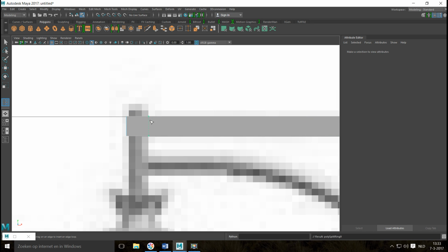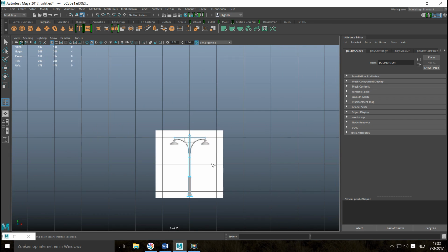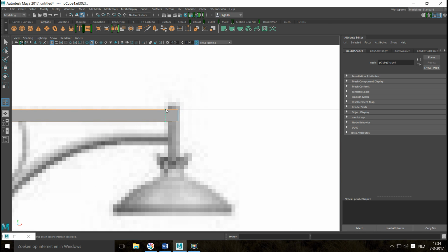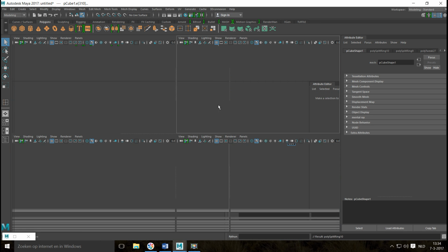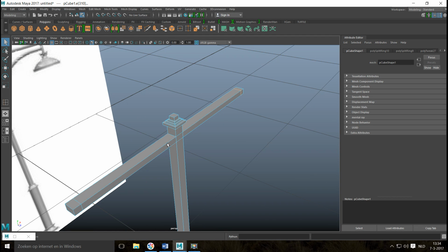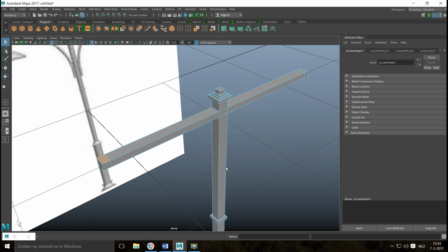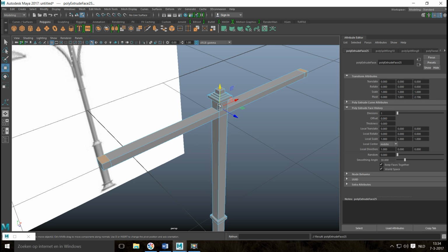and we'll add one here. That's a bit far out. And we'll add one here. Okay. Q on a keyboard. We're going to jump into this view. We're going to right click on a face, select that one, and shift select that one. Hit Control E to extrude, W to pull up just a little, and then we're gonna see if we got the same thickness.